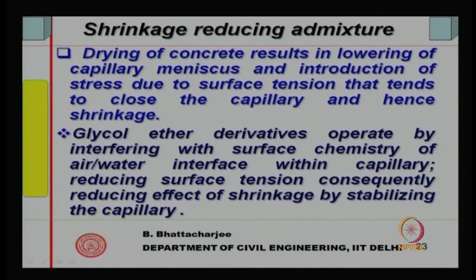Then there are shrinkage reducing admixtures. You see, drying of concrete results in lowering of the capillary meniscus, and since the capillary meniscus lowers, stress is introduced due to surface tension forces.